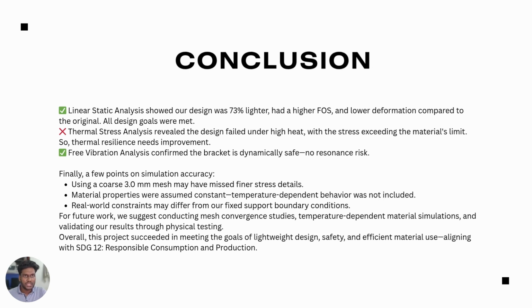Conclusion: linear static analysis showed our design was 73% lighter and had a higher FOS and lower deformation compared to the original. All design goals were met, but thermal stress analysis revealed that the design failed under high heat. Free vibration confirmed that the bracket is dynamically safe, with no resonance risk.